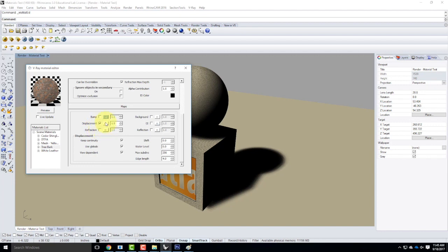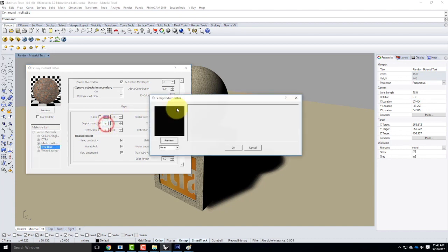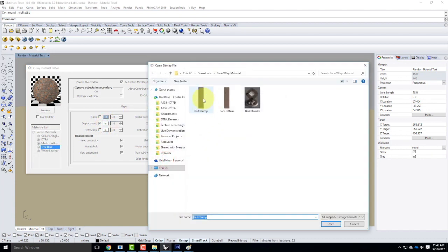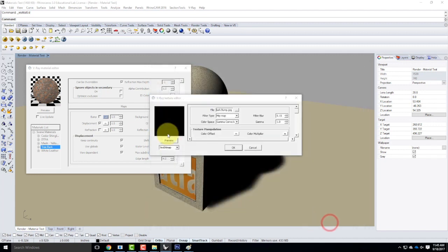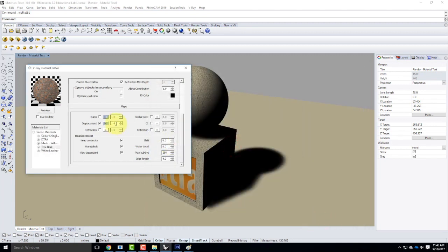And again, I didn't create it, so I don't know their strategy here. But if I click on the M and I load up that same bump map as a texture, as a displacement map, I think about what's the biggest distance in this surface that I want to have. Maybe the bark has maybe an inch groove to it, so we'll do it at 1, or maybe 0.75. Try that. We can give it a preview. See what it looks like. OK, we'll leave it like that.